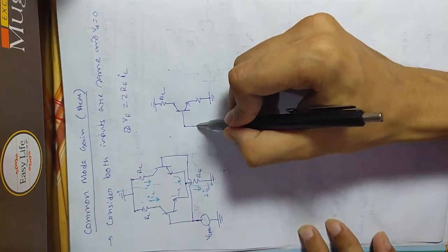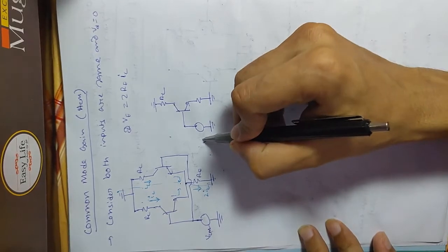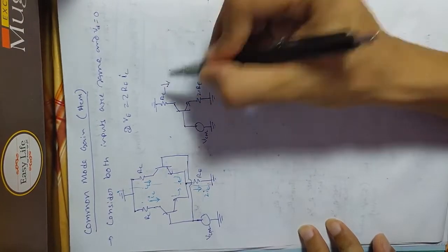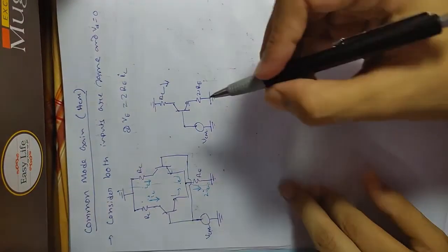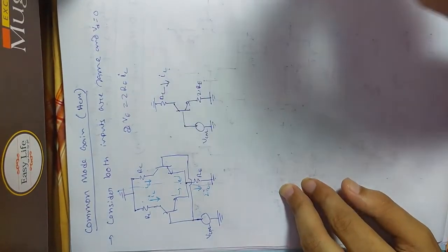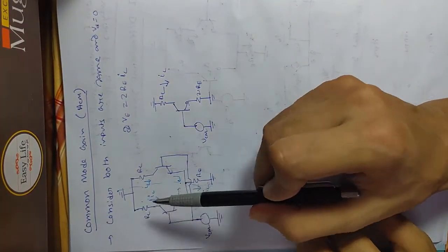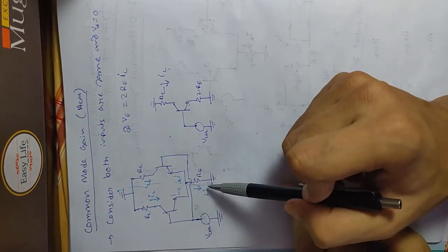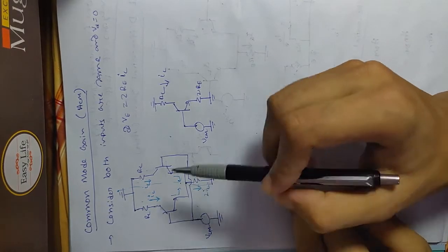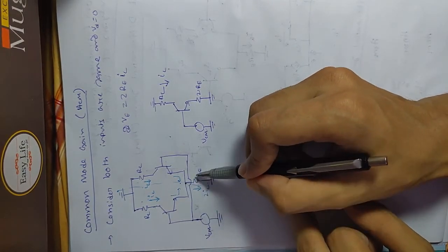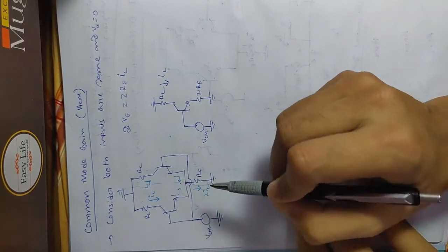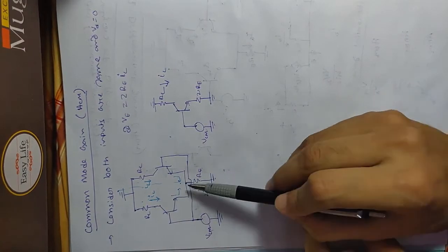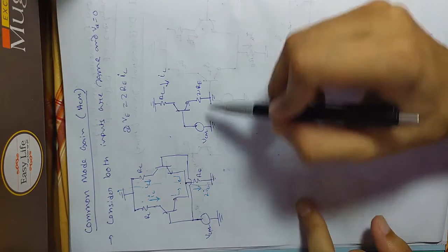RC, that is VCM, and that will be 2RE, because for the single branch current is IC, and if I consider emitter current and collector current are almost equal, then we can consider that this current is almost twice of the IC. So with respect to IC, if I consider a current flow IC, the same thing will be considered by doubling the resistance. So you can double the resistance, or you can double the current to maintain this voltage. So in this case, we'll replace RE by 2RE.